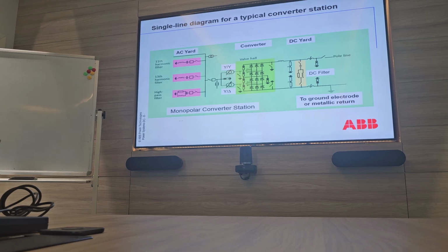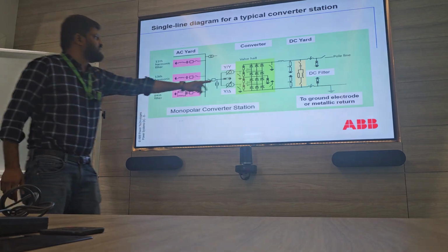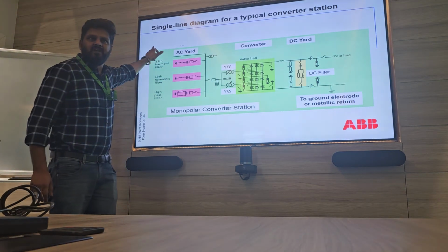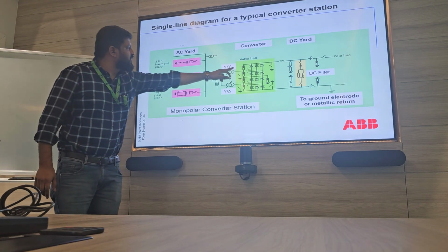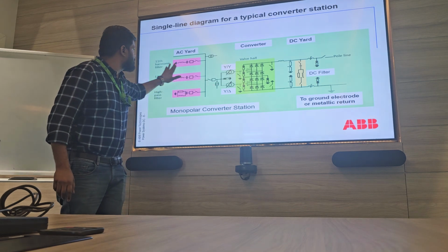It's similar to what you said before about synchronization. We have these valves, correct? Valves produce the harmonics, so these harmonics we need to suppress here. Otherwise, the harmonics will flow from here to the network grid. So all the harmonics produced by these valves will be suppressed here.